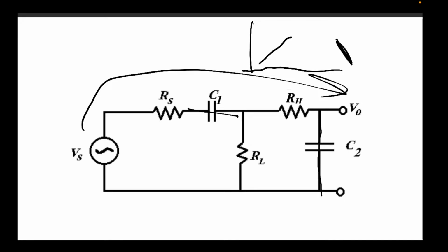So maybe you can intuitively think, in the middle, it's probably not 0, probably somewhere flat. And then there will be some frequency here, FL, and some frequency here, FH. So for a simple circuit like this, you can easily derive a transfer function, just by looking at the properties that these capacitors hold, or where they are.